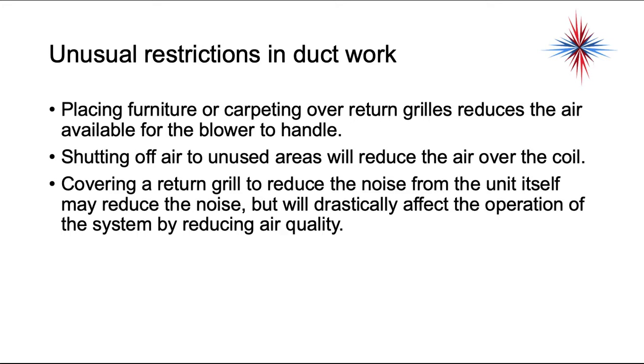Okay, and we've cut in half the amount of CFMs that are available to go after the coil because air has to go someplace. You shut off the registers in an unused space, all of a sudden you can't push that air to any place. So you've reduced airflow. Covering a return grill to reduce noise from the unit itself may reduce the noise, but it will drastically affect the operation of the system by reducing air quantity and quality.